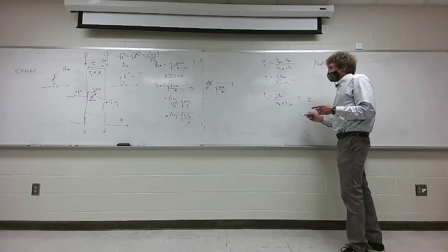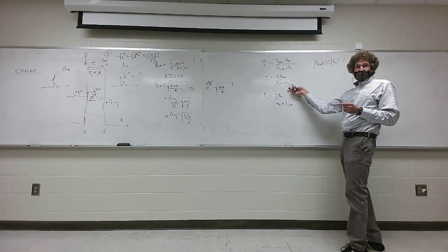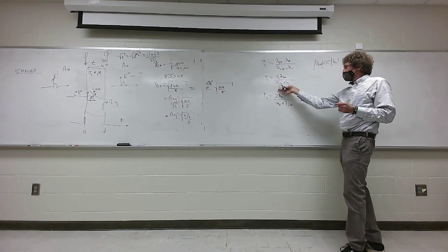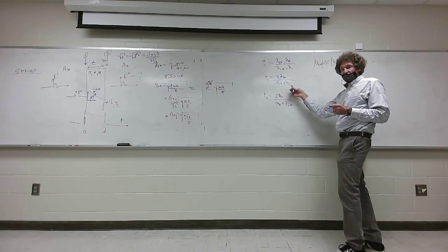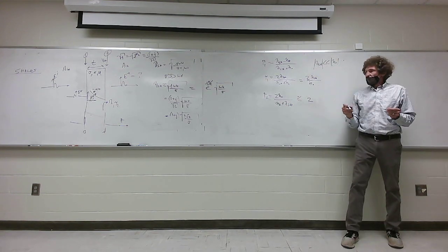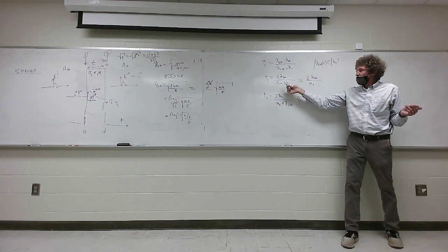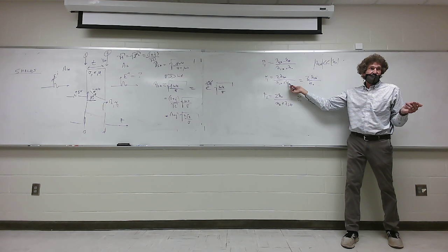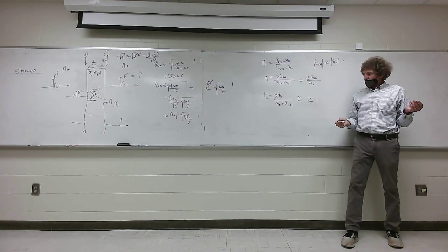Now, when I look here, what does that transmission coefficient become approximately? Tell me about this. If eta shield is much, much less than eta naught, what do you see happen? This becomes just 2 eta shield over eta naught. Y'all see that? Take a look. Eta shield's much less than eta naught. Say this is 1 ohm, this is 377 ohms. It's about 377 downstairs, right? Divide that into eta shield. Y'all follow me?